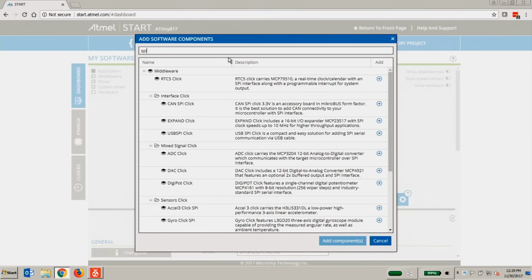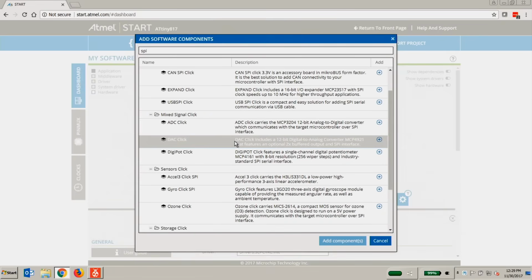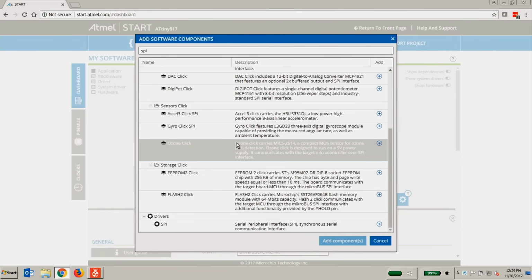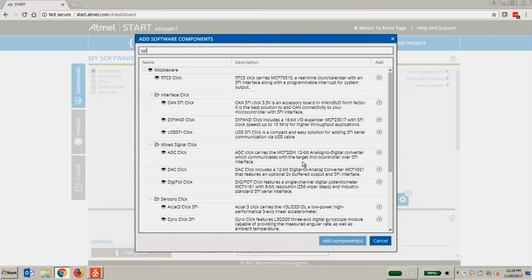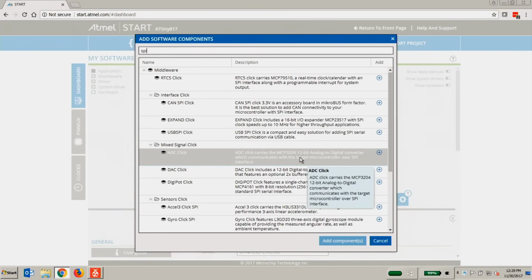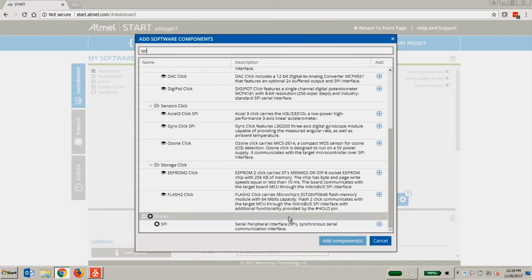Then you would not only see the SPI module for the AVR, but you would also see the UART, because that can do SPI master mode. Or rather, it would take you to that later on, because it would allow you to select the SPI, and that could then run from different modules. So there's a lot of abstraction here, but it will be very clear as you move forward in the different steps.